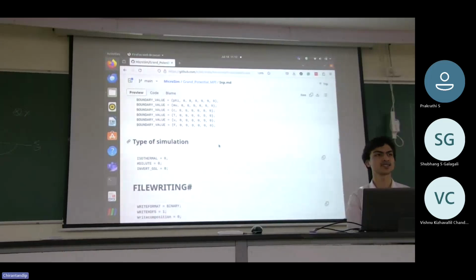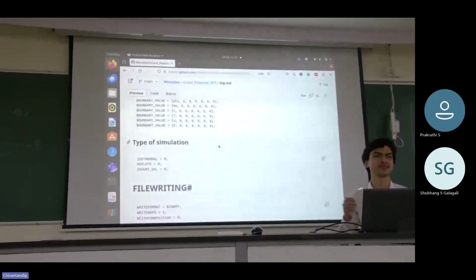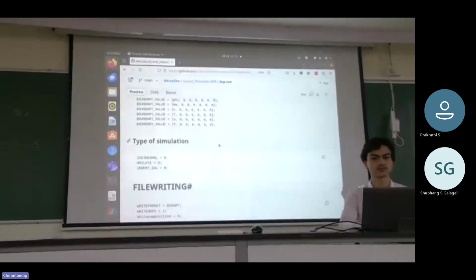One more small flag is the matrix inversion using GSL. Earlier for the dmu by dc matrix, we had to invert it to solve for the chemical potential. So remember you had that matrix inversion term for the mu calculation. Previously we were using our own routines. There is now a flag to possibly use the GSL routine if you do not want to use our routine. We have not found much difference between the two routines. Maybe the improvement was 2%, but it will show up with 11 components. Don't expect too much, but still, if you want it, you can just revert to the GSL matrix inversion. There's a flag that you can use.